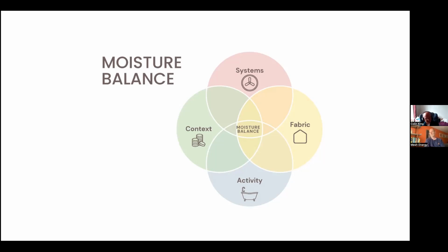When we looked at Part F 2 years ago, we went out and tested a lot of buildings, be it Passive House or new build or even retrofit. Over 90% of the systems that were put in were not meeting their design ventilation rates, or they had been installed incorrectly: things like insulated ductwork was actually just a flexible pipe, there were dead ends, there were condensate traps, and there were even some circumstances where I went out where the blanking caps had still been left on the MVHR when they were commissioned, so they weren't working at all. So it's about making sure that if we have these systems, they are commissioned and recommissioned seasonally to deliver the required rate. The new rates in Part F, and I would recommend that you actually look at new Part F, because the ventilation rates are far higher than they've ever been before.